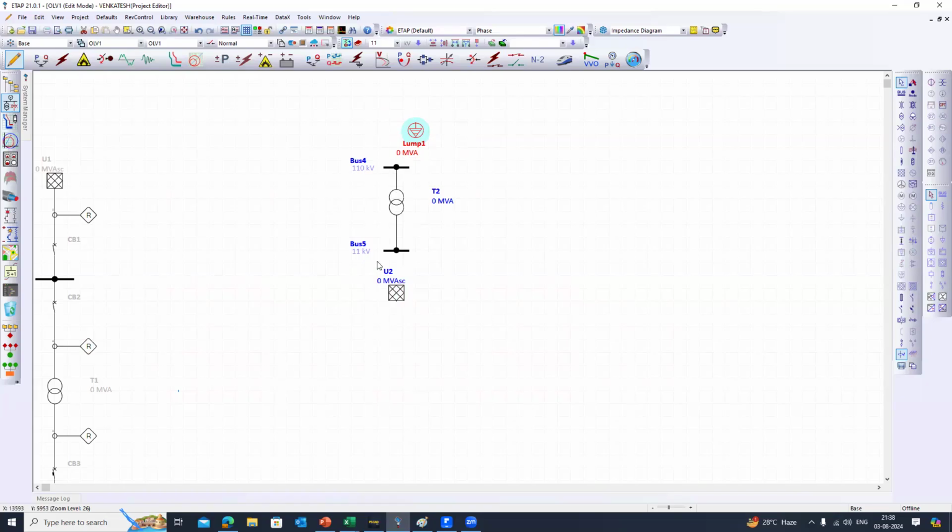Generally the transformer is a bidirectional device without any constraints, and the capability of the transformer is a circle to an extent. So we cannot really use the terminology primary and secondary, because power flow will be from bus 4 to bus 5 or bus 5 to bus 4, and it depends upon what is connected on bus 4 and what is connected on bus 5, right? I hope the terminology of the transformer is clear.